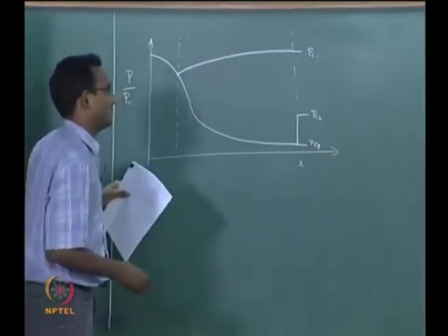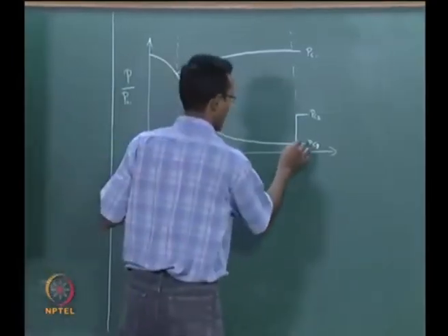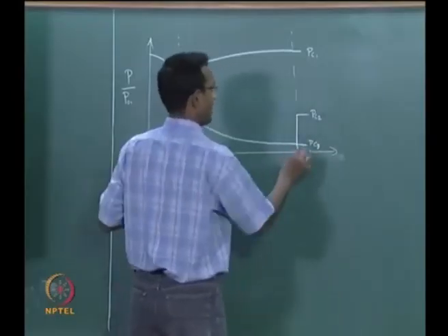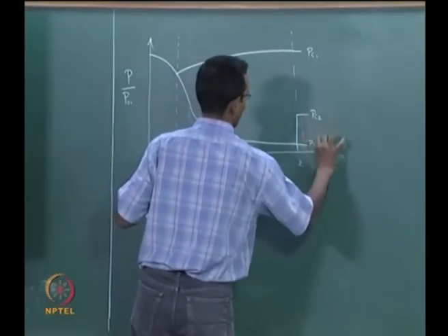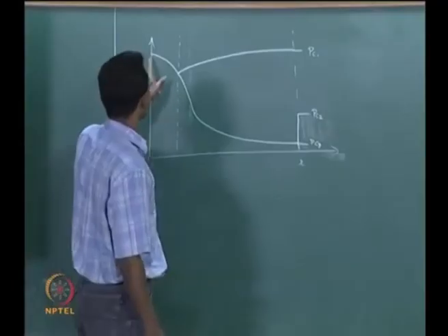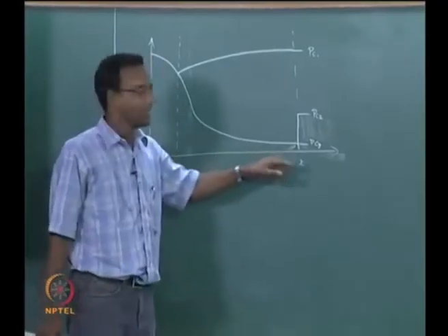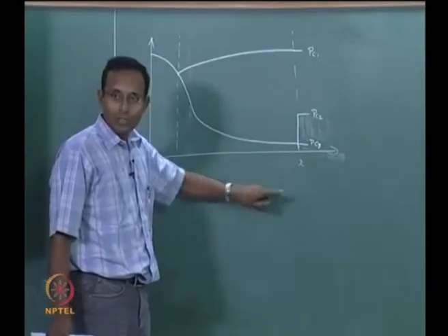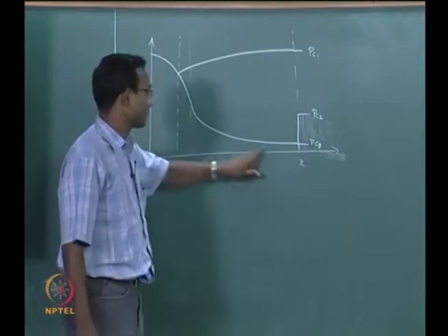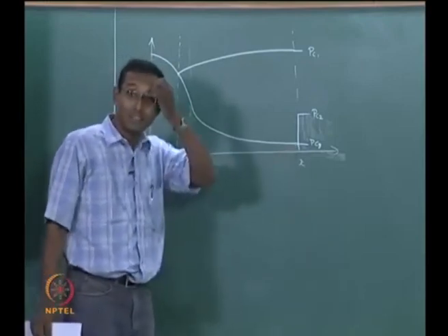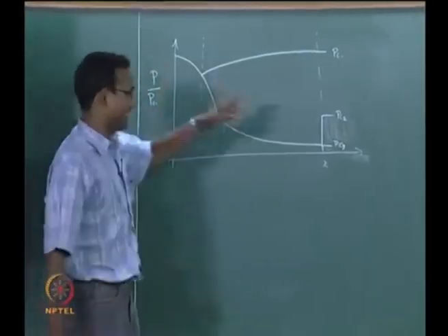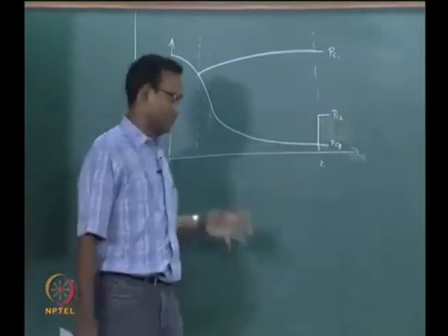We did all this, and then we said that if I decrease my pressure below this value, this particular region is called under expanded region. If it is in this region, it is over expanded region, and since previously we were interested only in pressure profile inside the nozzle, we said that anything below P critical 2, my pressure distribution inside the nozzle will never change, it will always be this particular curve. We said this and we were seeing plots of it also, and we discussed what will it be if P0 is changing and keeping Pb constant, etc. Those are all just variants.